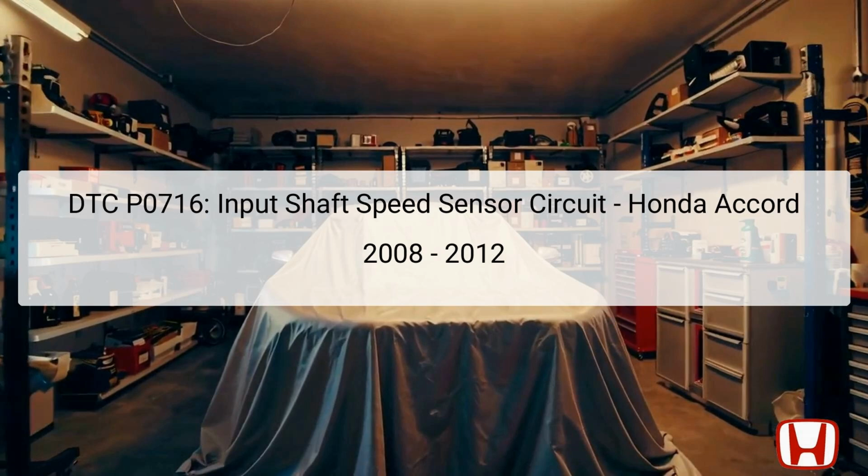This sensor is crucial as it provides data regarding the rotational speed of the input shaft, which helps the transmission control unit to manage gear shifts effectively. Problems with this sensor can lead to inconsistent shifting and can result in poor vehicle performance. We'll also touch upon related DTC P0721, which involves the output shaft speed sensor circuit.